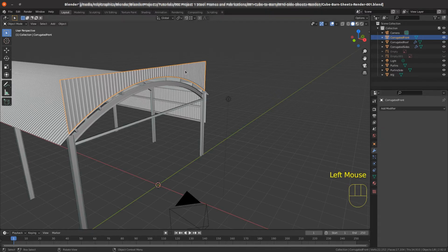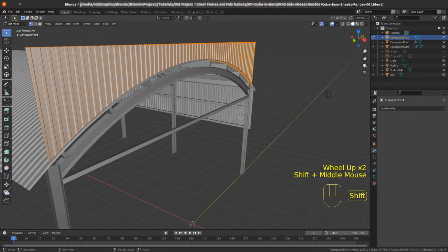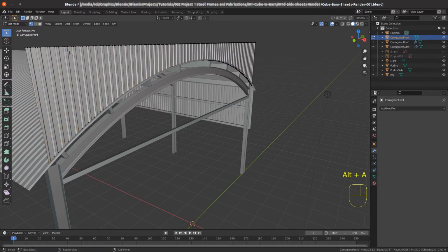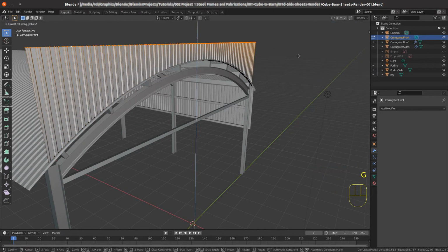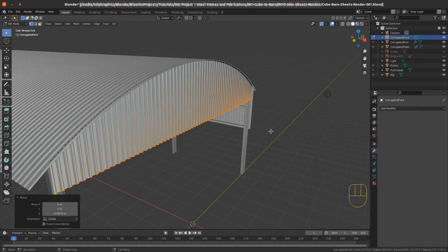That makes the mesh object the curve but the wrong side of the barn. So we could drag everything down below from above. That may mess the normals up, but I'll try that first of all. So Alt A to deselect everything, select the top edge, and then grab Z and drag it down. I'm going to drag it down so it's just below the purlins.